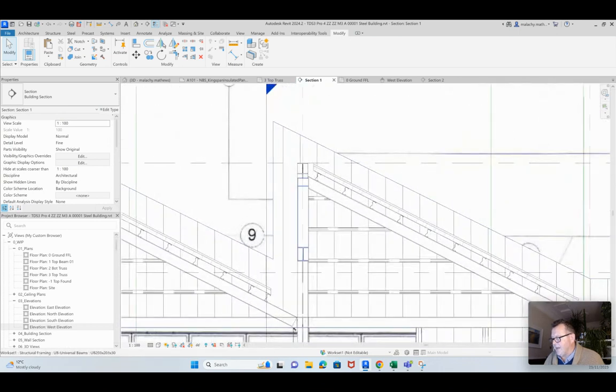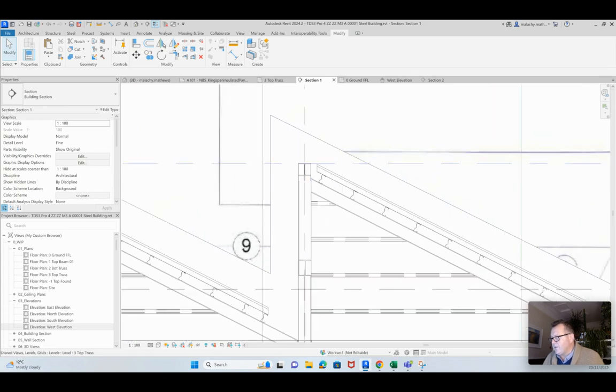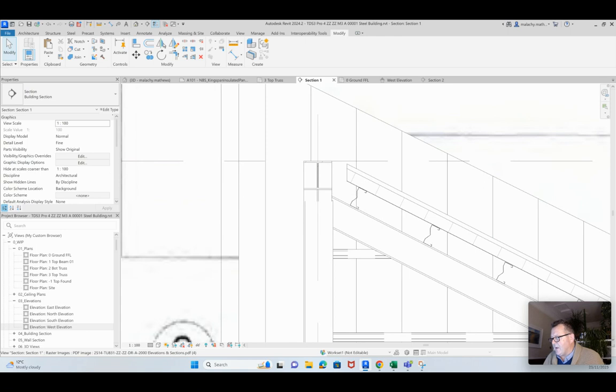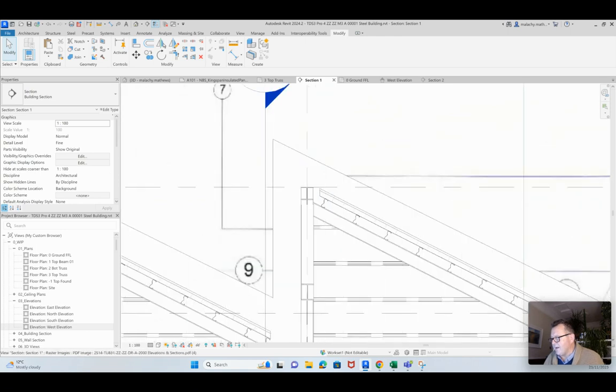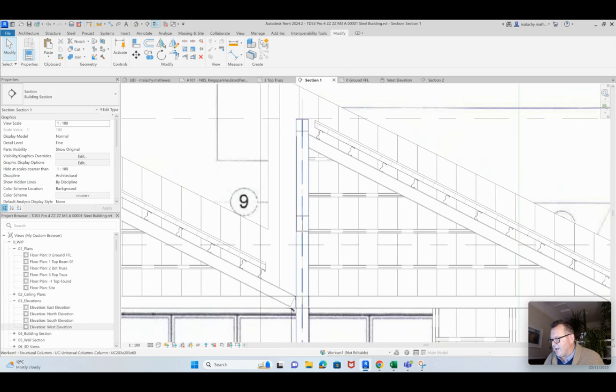And so this is what I have. Here's my frame, if you like, my beam and column frame coming down. So what I'm going to do is place a C channel here, which could be welded on there. And I'll put another one in around down here, something like that. Now that's going to give me a fixing that I can run the quad core wall panels all the way down to about here, something like that.